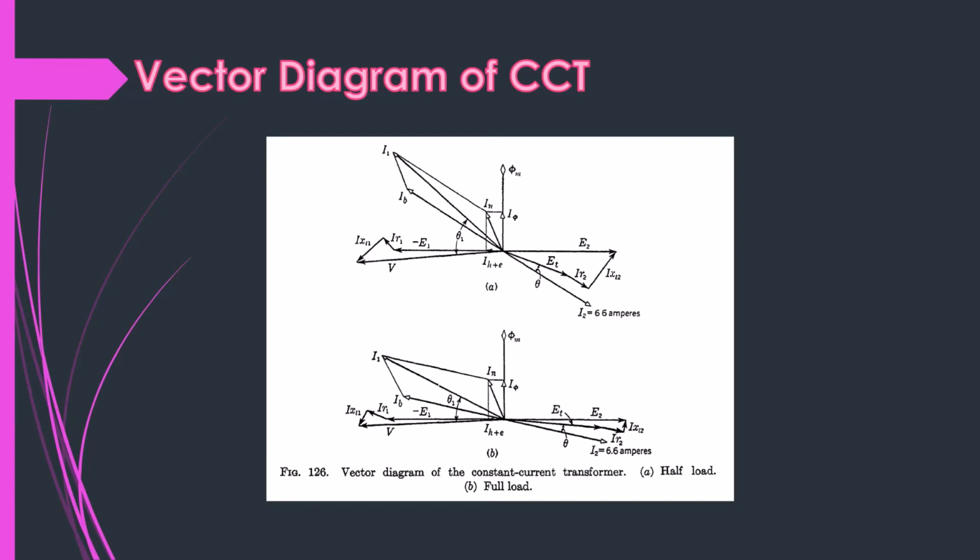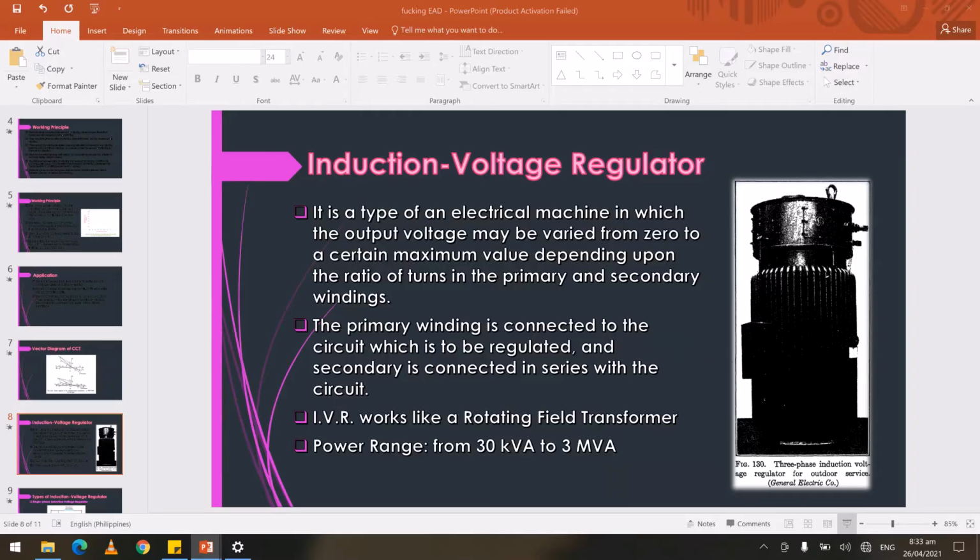Except for this, the constant current transformer operates at constant primary current and voltage, but with a variable primary power factor. Even though the secondary load may be purely resistive, the primary power factor of such a transformer is very low at light loads owing to the leakage reactance.